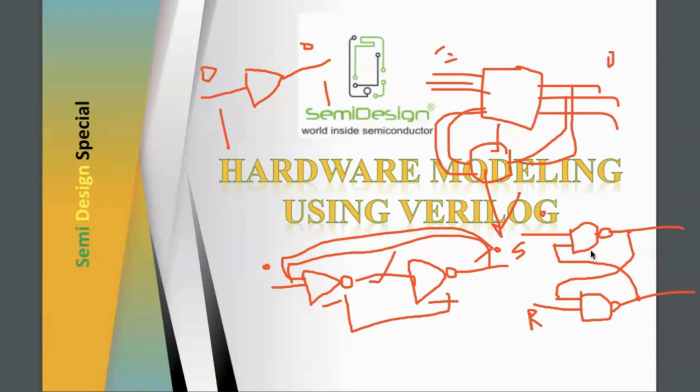What is the drawback of the latch and why are we moving to the flip-flop? Here the SR latch, JK latch, D latch or T latch, every one of them works like a memory. Whatever memory element we use, they are nothing but latches and flip-flops. The latch works very well as a memory element, but why are we moving to flip-flops? Because the latch is level triggered, whereas the flip-flop is stable and only changes at the edge triggering.